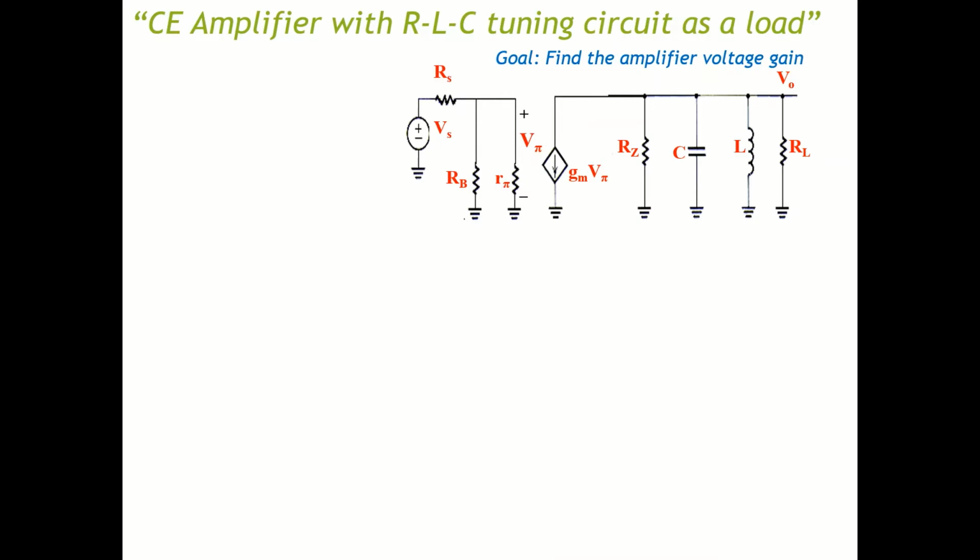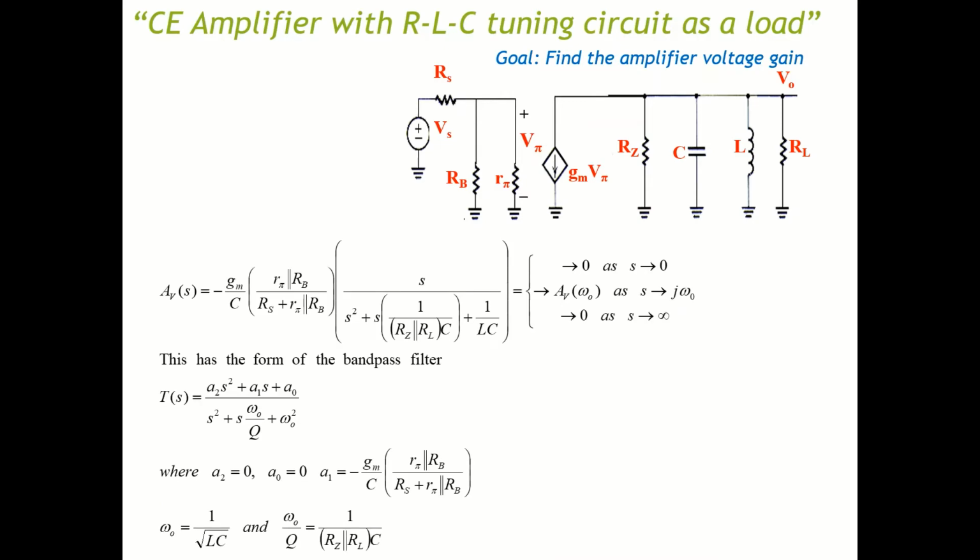So what do we find next? We want to analyze something in this bandpass filter. If you look at the frequency term here, which is s, okay, it's in the s domain, but you can plug j omega back in for s. What you see here is when s goes to 0, this whole term will go to 0, right? Therefore, gain is 0.